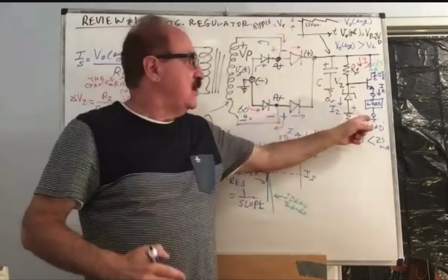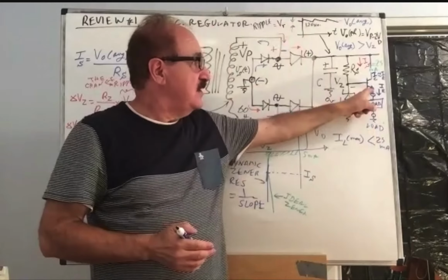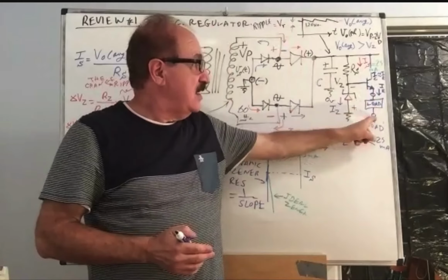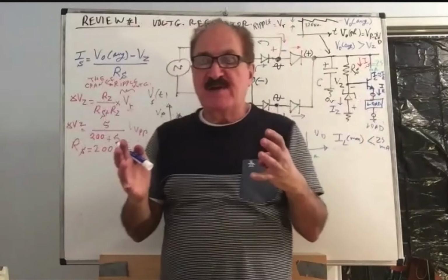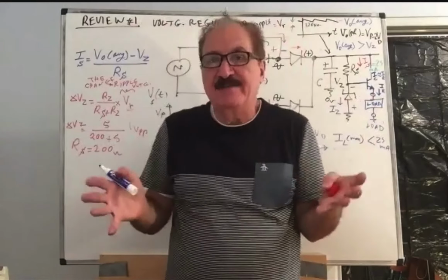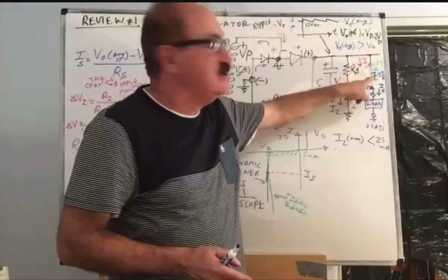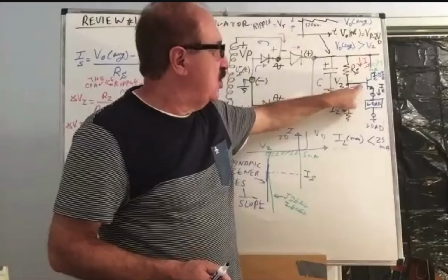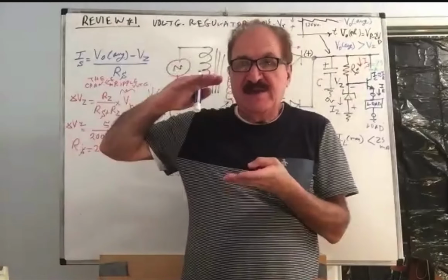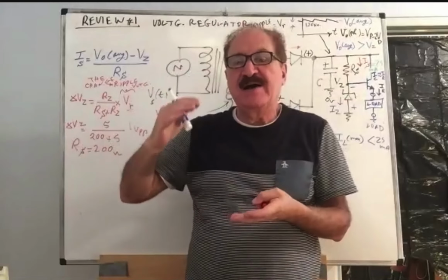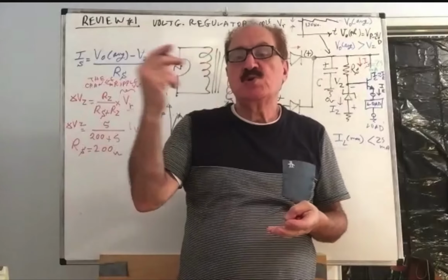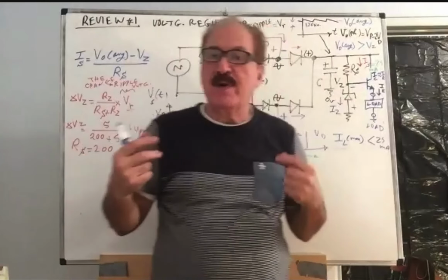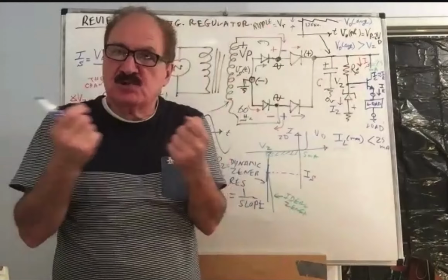So if the load current in this branch changes by a factor of 9 times, IC will change 9 times at the cost of VBE increasing by 25 millivolts.